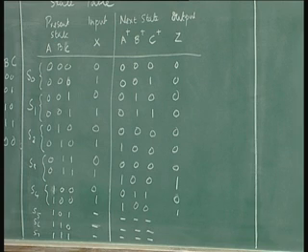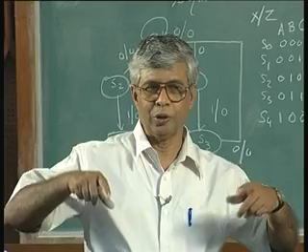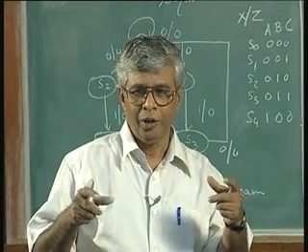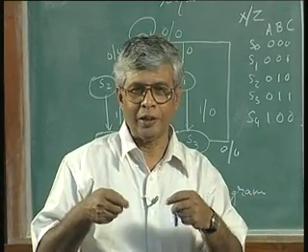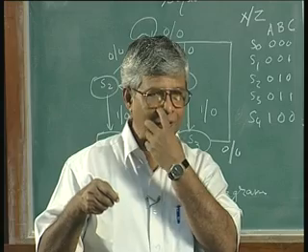It is also possible, in advance, this is an elementary level of treatment. At a slightly more advanced level, when the state transition has to happen, a don't care state may occur between two states whose output is 0 or two states whose outputs are 1. By making it a 0, we are causing a glitch. Do you understand what I am saying?